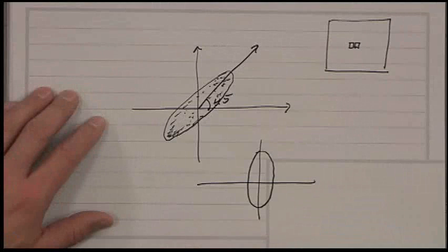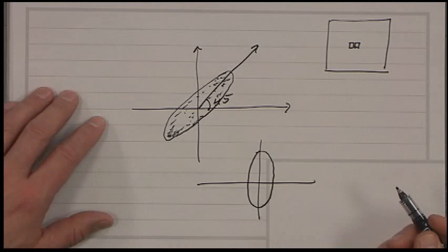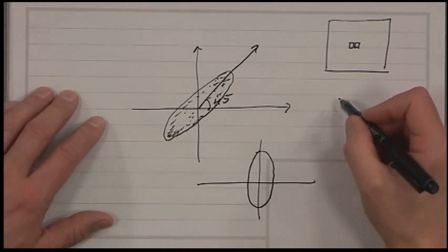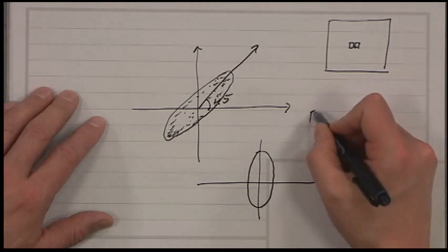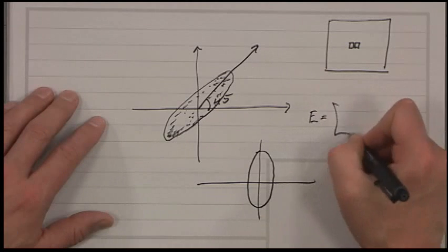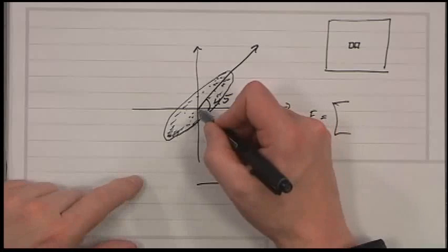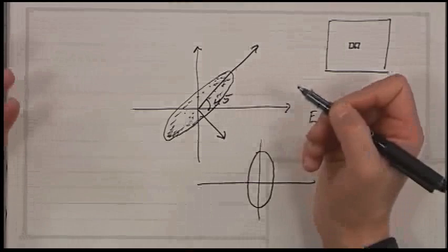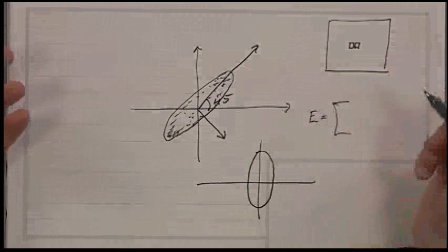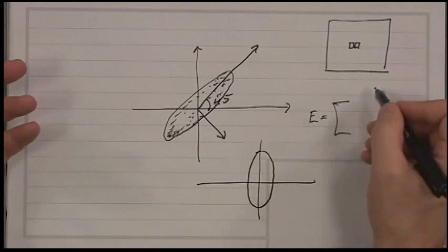So you almost know what the orthonormal transform has to be that will decorrelate a pair of pixels. It's got to be 45 degrees, by symmetry, assuming it's a stationary random field.